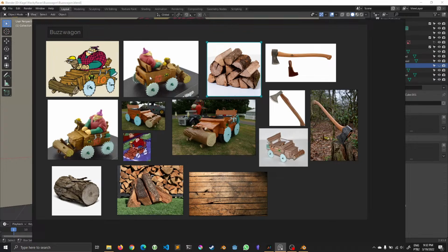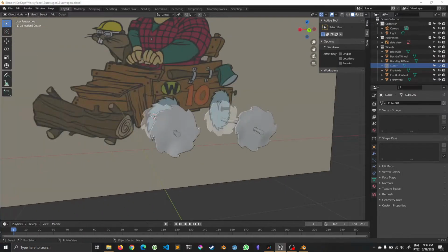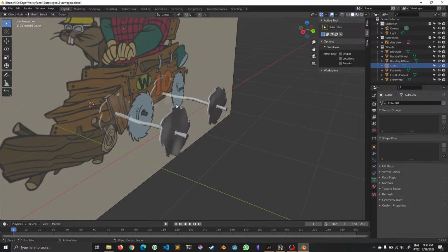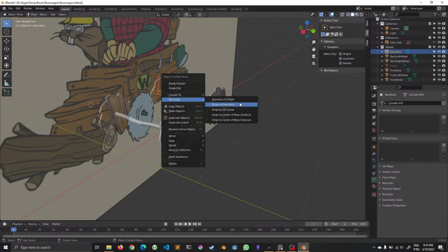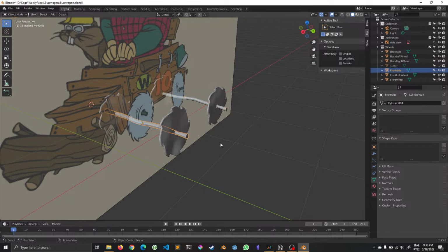And we can also carve the box so we can put the chair inside. Yeah, seems like a good idea. So let's put a box there. Let's just make sure that I have applied all the scale things. And let's set origin to geometry here. Okay.